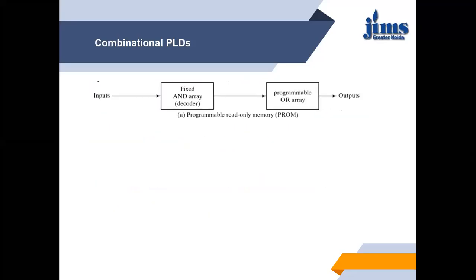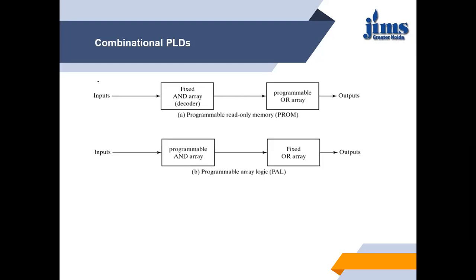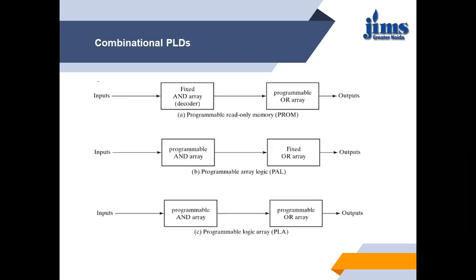So here are the block diagrams. PROM: fixed AND array, programmable OR array, and the AND array is nothing but the decoder. In PAL, programmable array logic, AND array is programmable, OR array is fixed. And we have PLA, programmable logic array, where both the AND array and OR array are programmable.